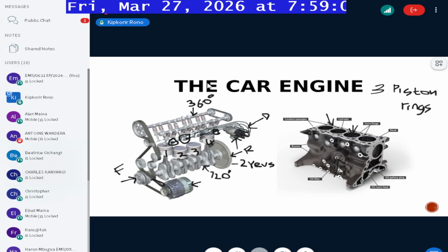The air filter is normally just to protect the integrity of the air that is going into the intake manifold. Because if that filter is, say, for example, blocked or choked, then you will have less quality of air going into the intake manifold, which means that it affects the efficiency of your engine, especially in terms of fuel economy. So it's usually just recommended that they be changed together, but where possible, if you're operating in a very dusty environment, change the air filter as often as you can.